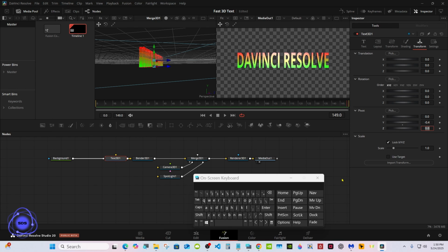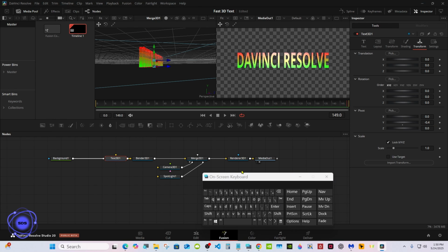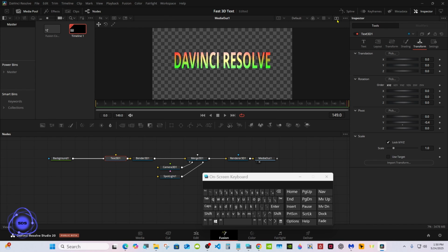Minus 0.4. We'll animate the text in first. We'll go to one viewer for this. Under translation, take the X, move your text all the way off the screen to the left. Make sure your playhead is on frame 0.